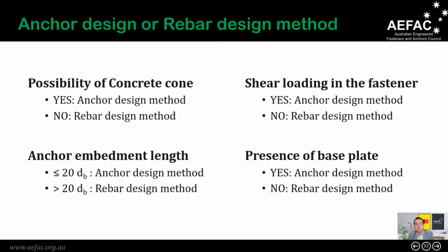So I have highlighted 4 guidelines to select the proper design method in this slide. The first one is whether there is a possibility of formation of concrete cone. If yes, then the rebar model cannot be used. So we have to use the anchor design model.